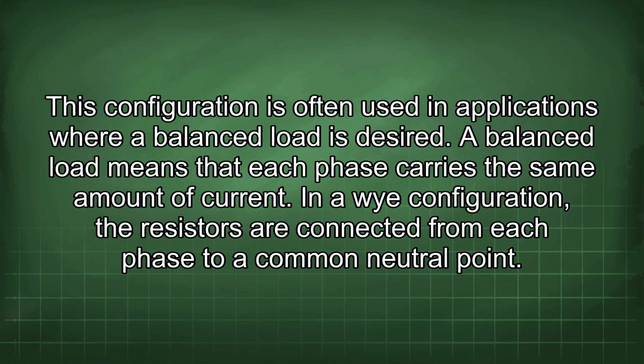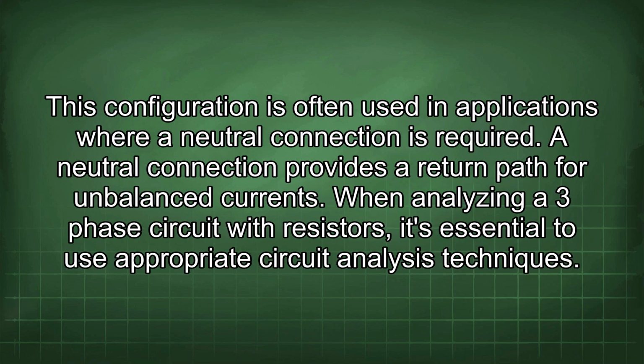In a Y configuration, the resistors are connected from each phase to a common neutral point. This configuration is often used in applications where a neutral connection is required. A neutral connection provides a return path for unbalanced currents.